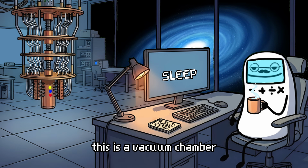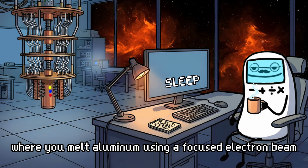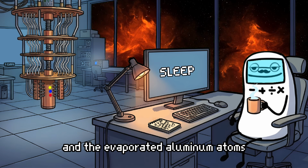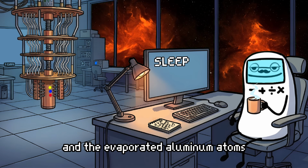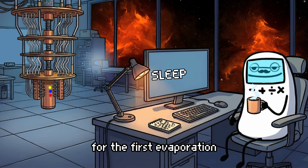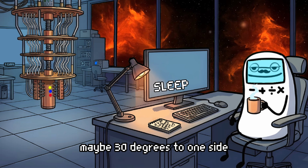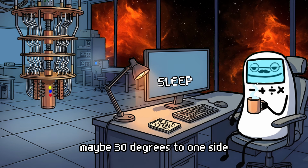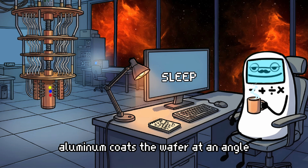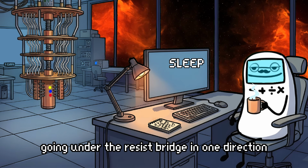You put this patterned wafer into an electron beam evaporator. This is a vacuum chamber where you melt aluminum using a focused electron beam, and the evaporated aluminum atoms fly out and coat the wafer. For the first evaporation, you tilt the wafer at an angle, maybe 30 degrees to one side. Aluminum coats the wafer at an angle, going under the resist bridge in one direction.